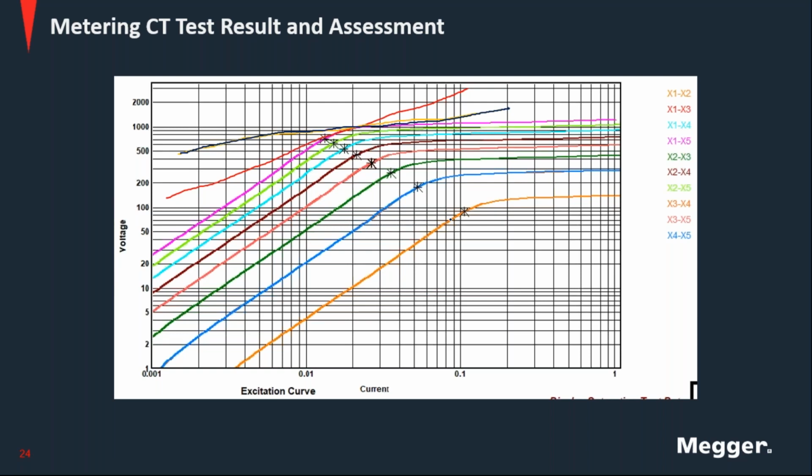You continue that one, and where they intersect, if they intersect outside of the characteristic, you would bring a straight line across perpendicular to the characteristic, and that would be the definition by IEC of the knee point. Okay, thanks, Volney. Thank you, Bill.